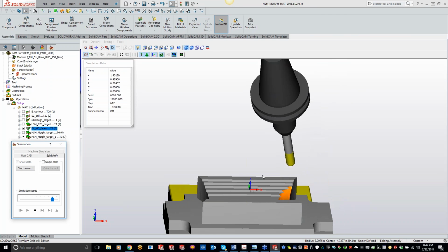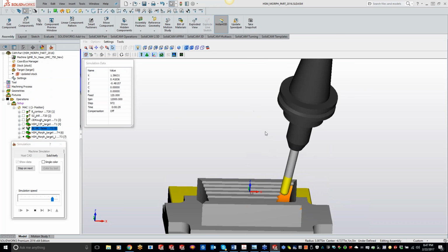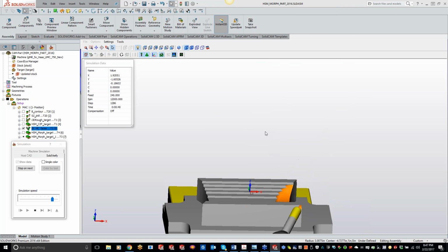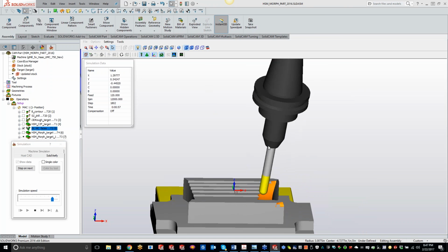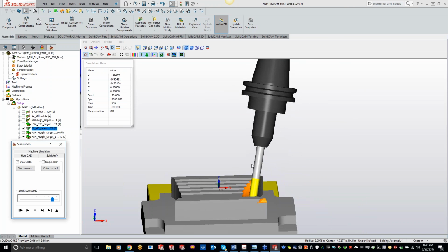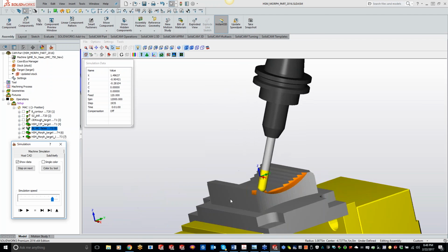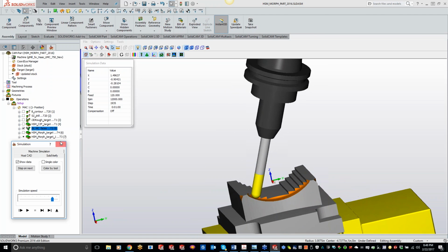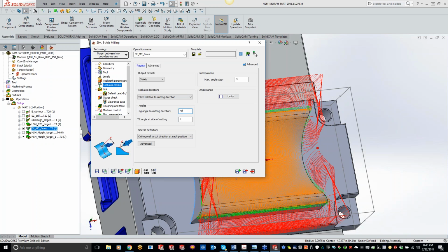So right now you can see that our cutter is actually angled at 20 degrees. And obviously I need to set up some areas so it doesn't touch, but let me just pause this, and you can kind of see that we're using the side of the cutter going through that cut versus going straight down using the bottom of that ball. So we're actually using the side. If I want, I can kick that over a little bit larger to maybe 40 degrees here.